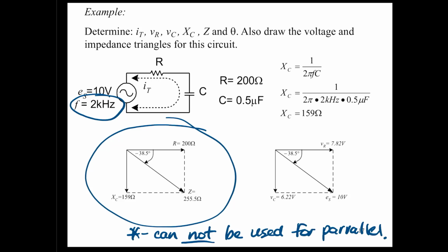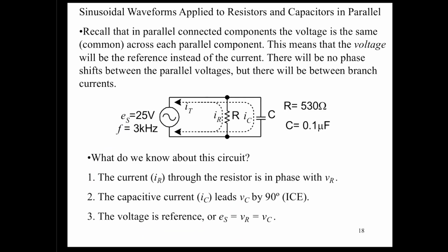If you were going to show me a sum of impedances adding together to give you a Z total for a parallel circuit, you'd be telling me that two 10 ohm resistors in parallel equals 20 ohms, and we know that's not right. So we have to use product over sum when we're looking at parallel. Let's make sure we understand that when we look at this example.